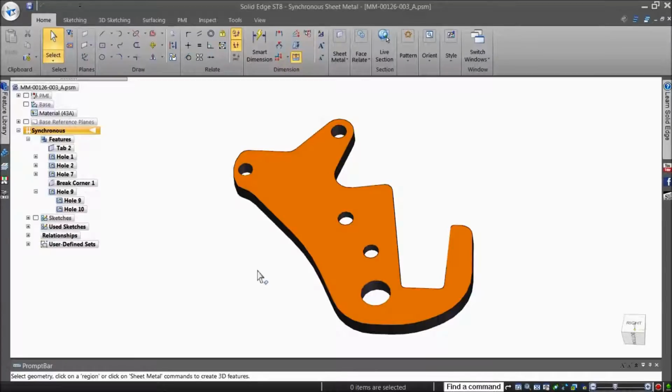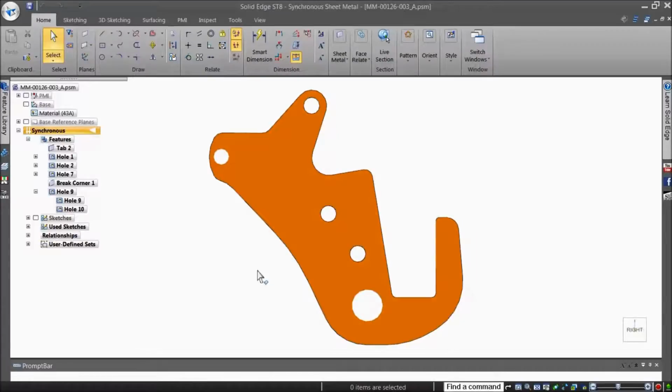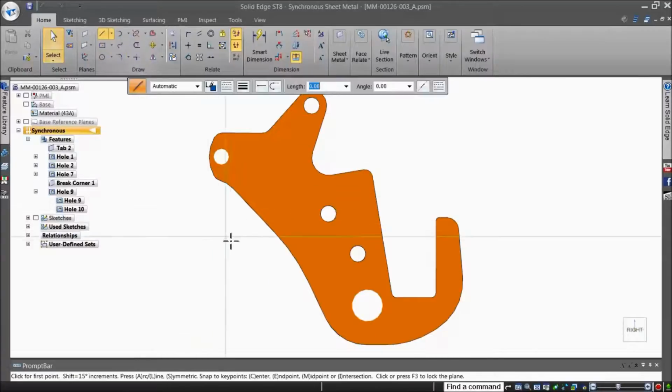Here are a couple of options. In the first example, you can add 2D construction geometry, a process that adds steps but provides further control. Create a construction line between two holes of the target series of holes that need to be aligned.